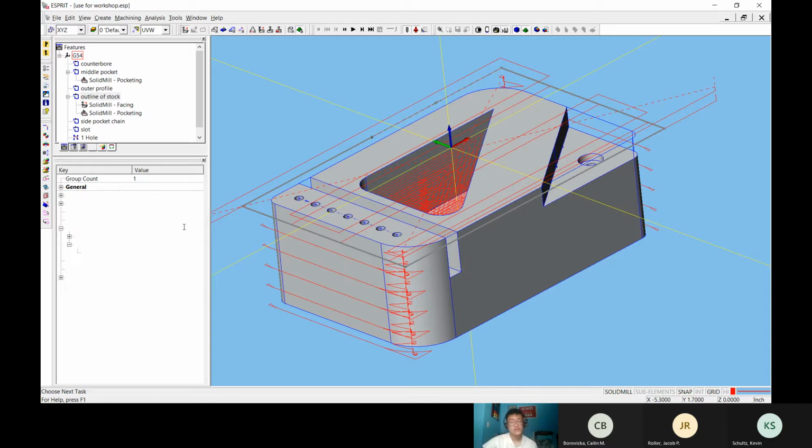That way, you're essentially allowing the toolpaths to go outside of the chain, which is sort of breaking the rules. So sub element, then go to attributes, and you'll get the option to change if your sub element is open edge or not. And we want open edge true so that it's able to move outside of the chain.